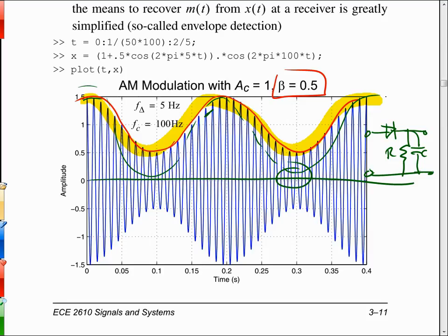So that's why AM radio was so popular in the early days of radio. The receiver is very, very easy. Everyone could own a transistor radio. Before that, they could own a vacuum tube-based radio. I mean, whatever. You could go to Radio Shack today and buy a crystal receiver. Has anybody ever played with one of those? Just a coil of wire and a little diode in this circuit basically, and a little earpiece. No batteries required. Just plug the ground wire into a ground in your house, like a heat duct or something,